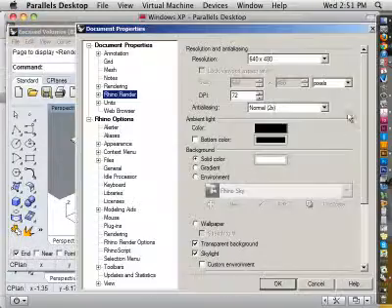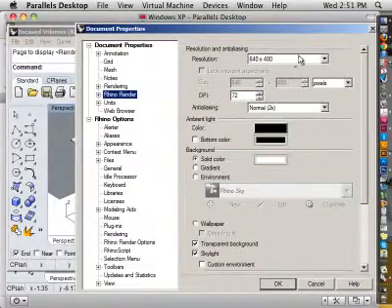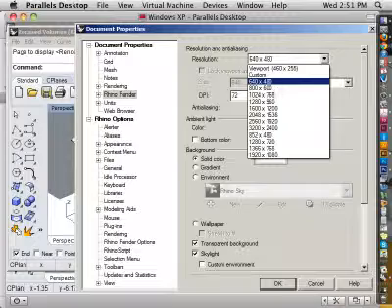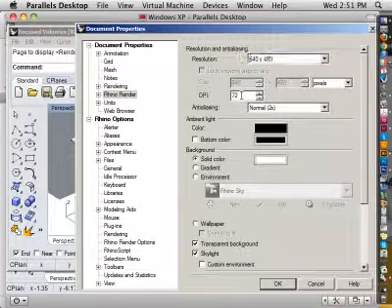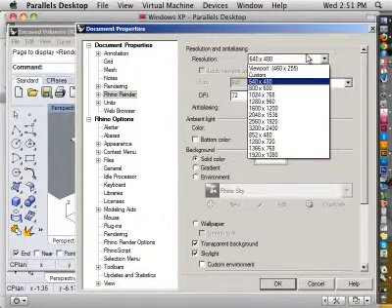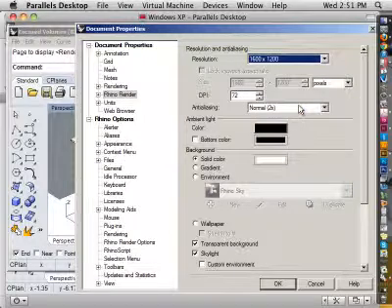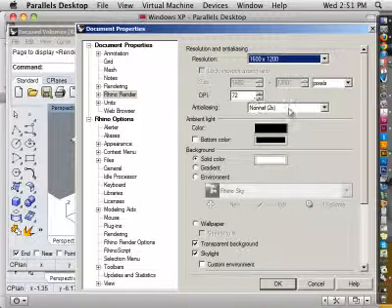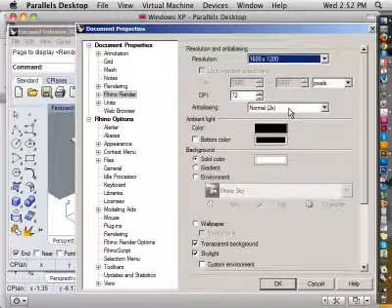and you can control the size. So this is the size in pixels, and then the DPI. So you might want to up this to 300, or you might want to change this to something like 1600 by 1200, just so that you get more graphic information to work with, so that you can either scale it up or that it can be looking correct at the size that you need to have it on your board.